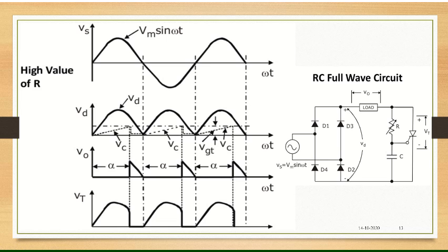Recall? Yeah. So similarly, the voltage across the SCR, VT, if you observe, initially it will be following the input, that is VD. VD is the voltage that is appearing to this circuit, the full wave rectified output. So every cycle you are having a positive response there.